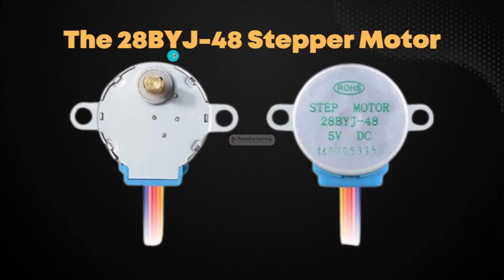So now let's see the 28BYJ48 stepper motor. It is a 5-wire unipolar stepper motor that runs on 5 volts. It's perfect for projects that require precise positioning, like opening and closing a vent. Because the motor doesn't use contact brushes, it has relatively precise movement and it's quite reliable. The only drawback is that it is somewhat power hungry and consumes energy even when it is stationary.